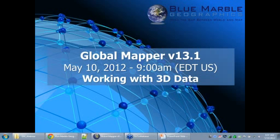Welcome, everybody. This 60-minute session will cover topics related to working in 3 dimensions in Global Mapper. Exploring real-world scenarios, we will examine placing models on your map or creating your own from scratch, and then viewing and analyzing the data using the 3D viewer. Workflows covered will include editing 3D data using the Digitizer, viewing 3D surfaces and models, and terrain analysis functions such as viewshed analysis, watershed delineation, creating terrain surfaces from LiDAR data or contour grids, and contour generation.